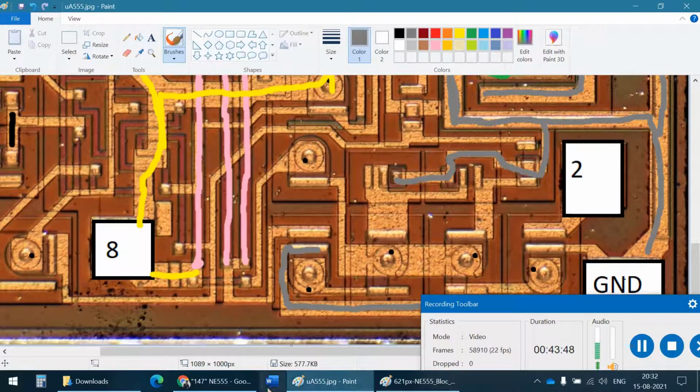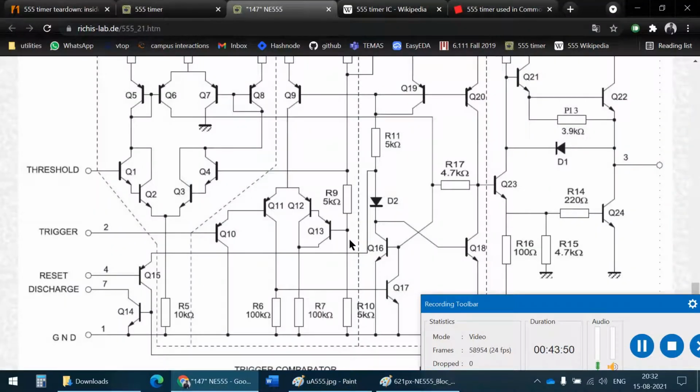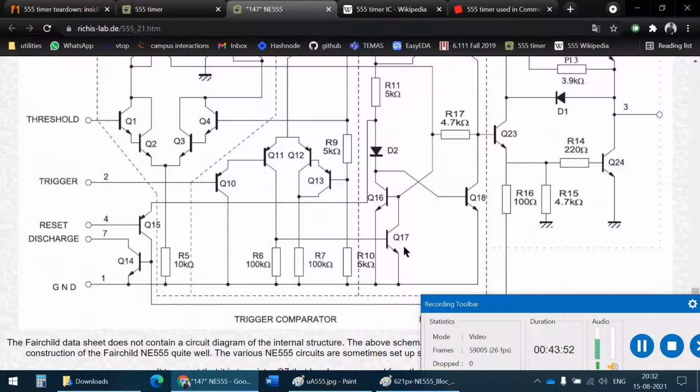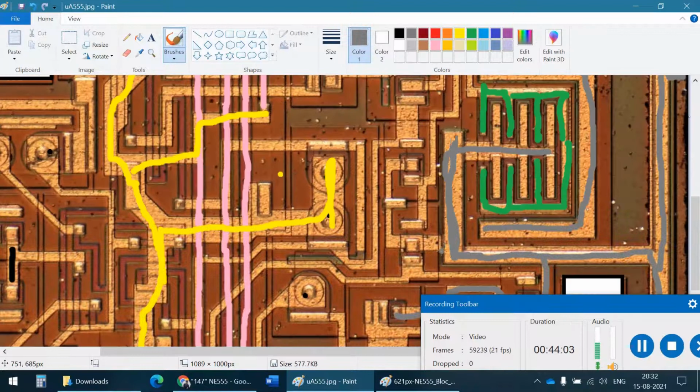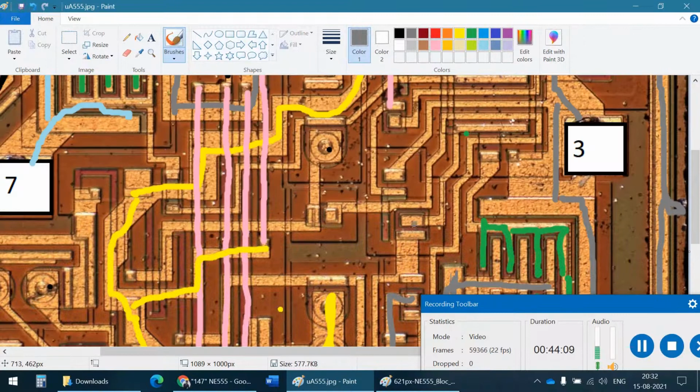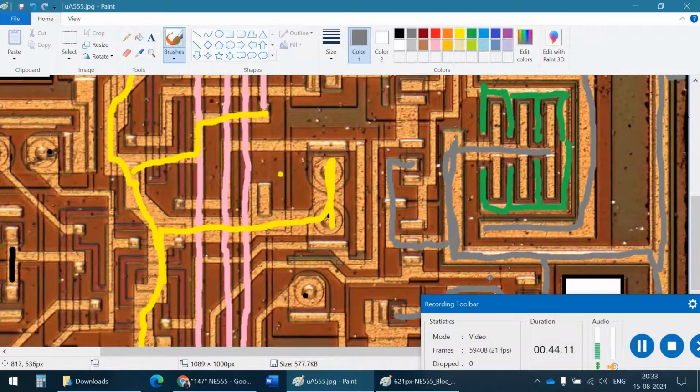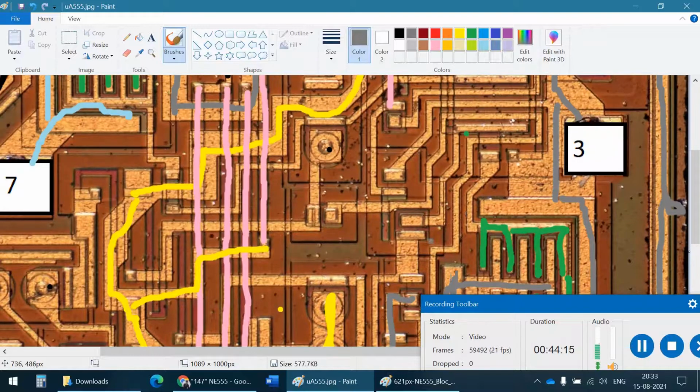Is it connected to ground? 16, 17, 18. Yeah. See, the emitters of all 16, 17, 18 are connected to ground, and you can see I just drew ground right through them. So I'm pretty confident that that's 16, 17, 18. It could be these as well. This also seems to be connected to ground. This one as well. So these two.